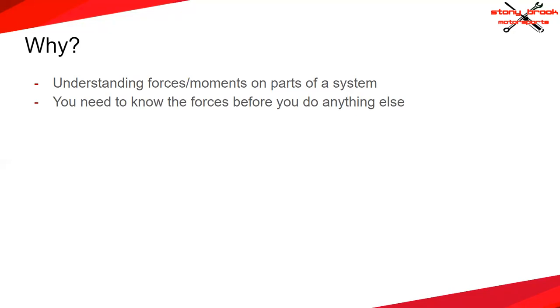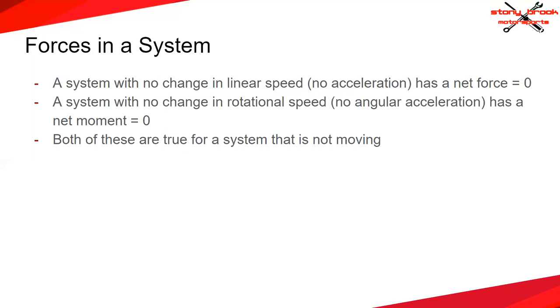Additionally, there are some cases where it might not break, but it might deform, and you also generally want to avoid that. With forces in a system, a lot of you know this by now, but it's important to put these concepts down right now because they really drive a lot of this stuff in statics. As most of y'all will know, a system with no change in linear speed, so it's not accelerating, has a net force of zero. Likewise, a system with no change in rotational speed, so it's not accelerating angularly, has a net moment of zero. Both of these are true for a system that is not moving or is in equilibrium.